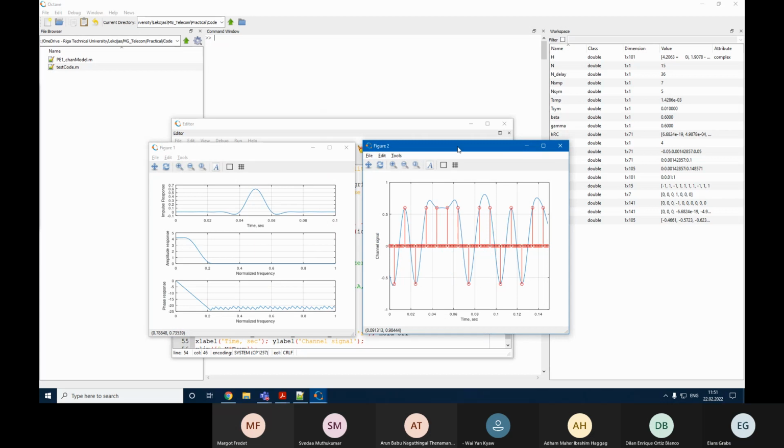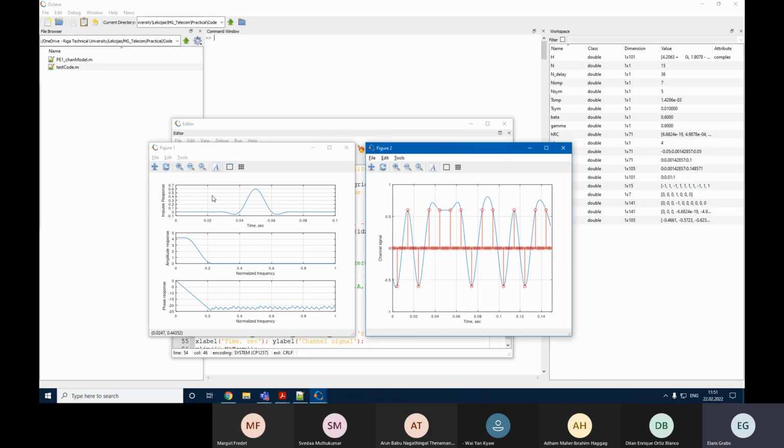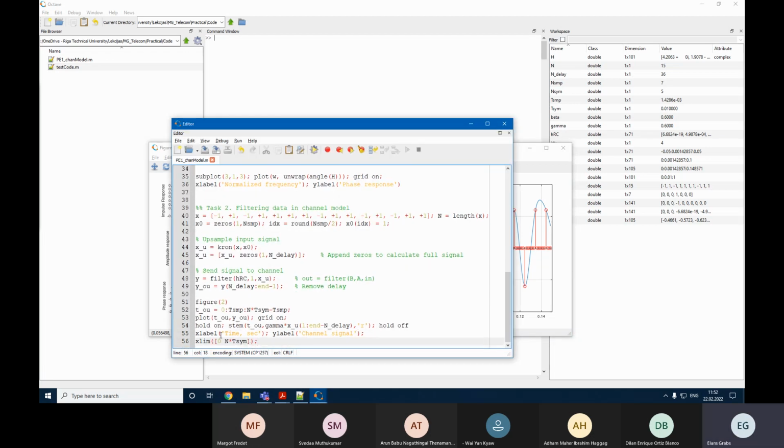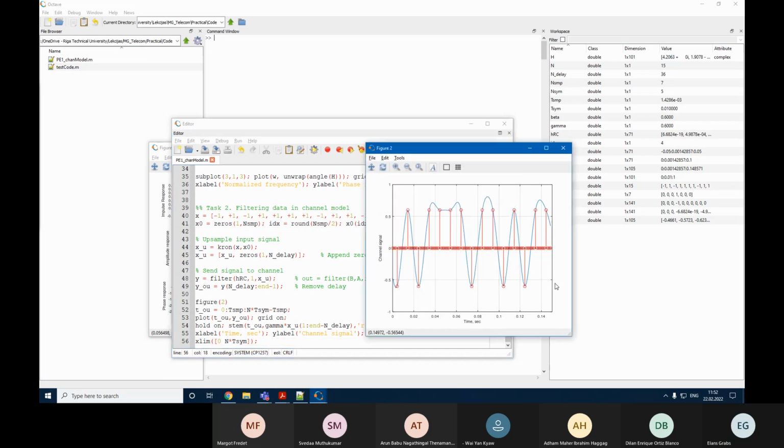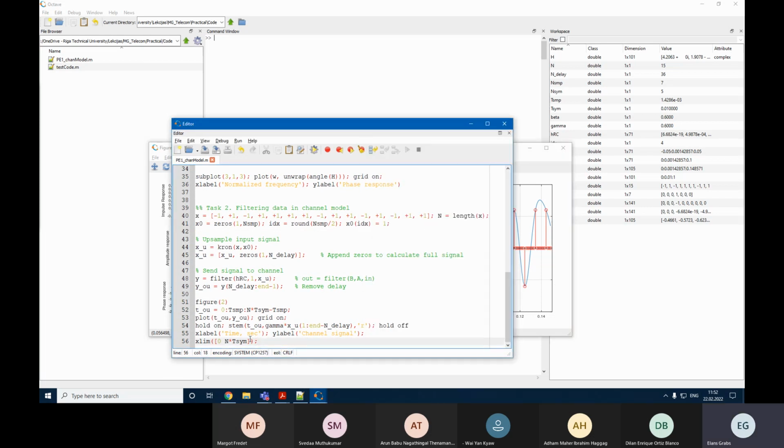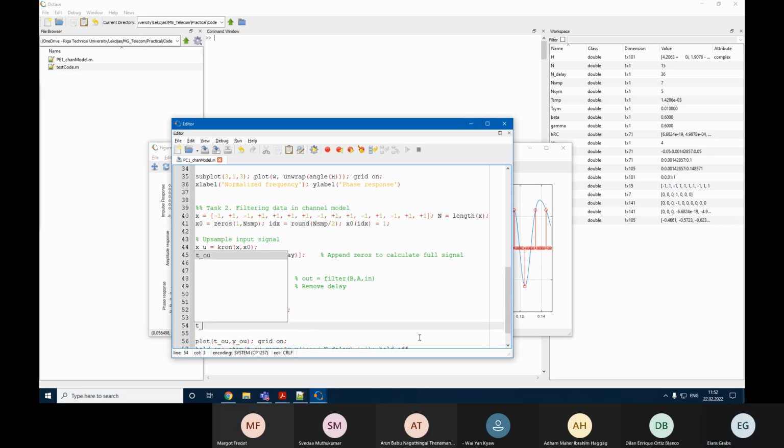Yes, like this. Now, what I would really want to do is to get rid of these zeros, yes, just to see the samples themselves. So for that reason, I need to, how to say it, downsample this time and this signal. So I'm going to do it like this. Yes, I'm going to need downsampled time and downsampled x. So basically t downsampled and x downsampled.